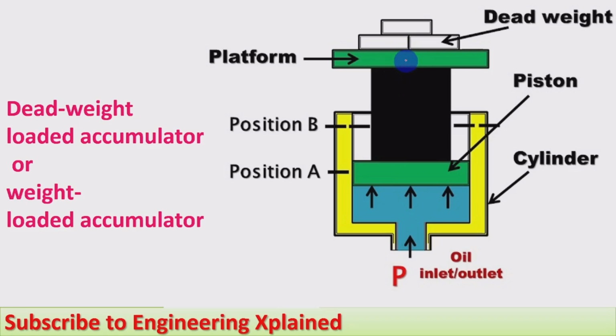There is a platform, and when the pressure in the system is higher, fluid enters here and lifts the weight in the upward direction, and that stores the energy as the potential energy of the weight. Initially it is at position A, and when it is lifted the piston reaches position B.